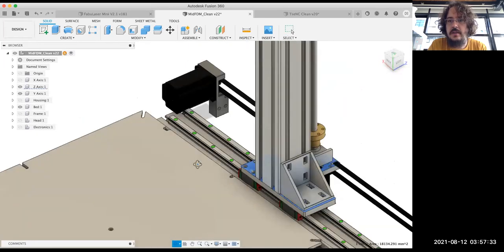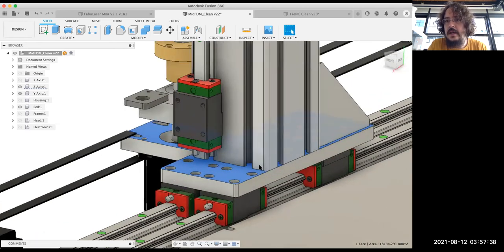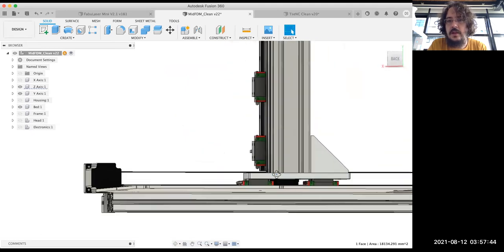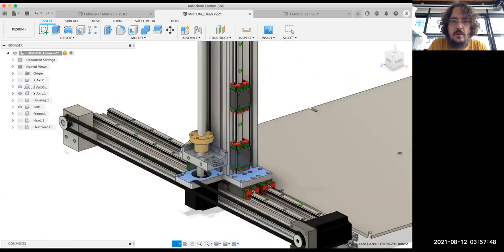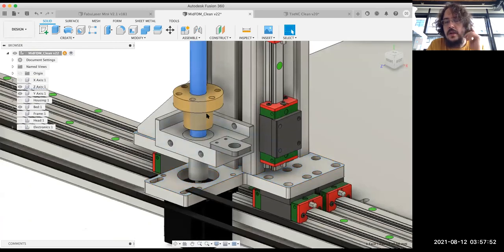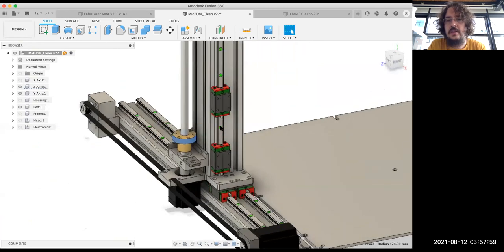It uses also this bracket on this other side, and the profile on the bottom is tapped. And the screws are passing through from the bottom here, and then this would attach also the profile from this other side. So then the motor has a coupler over here. Here there is a lead screw, and then there is a brass nut that moves the whole system up and down, and then 2 carriages and 1 linear guide over here.